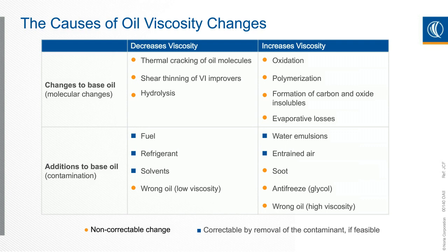It could decrease the viscosity or it could increase. And certain things could be introduced to the oil to cause an increase in viscosity. Water, for example, which by itself, the apparent viscosity is actually lower than oil. When it's turned to an emulsion in the oil, the viscosity actually shows an increase, and even entrained air.